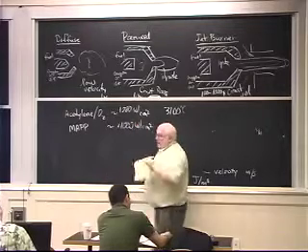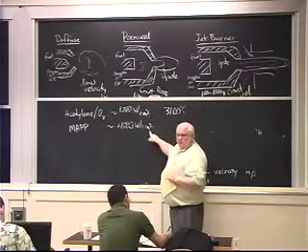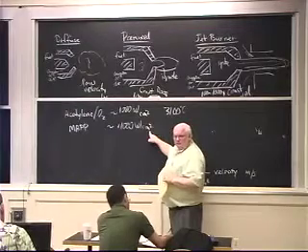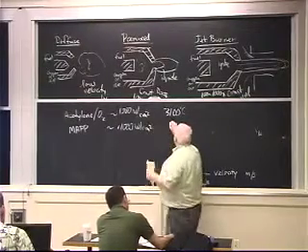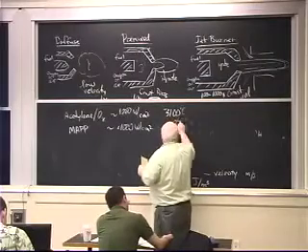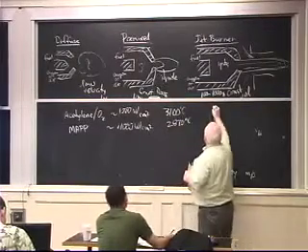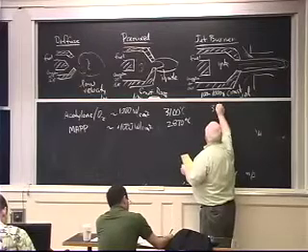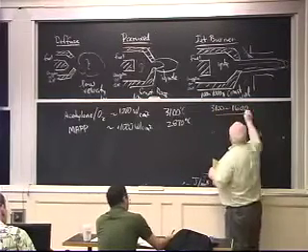It turns out you can weld with MAP, but instead of having a 2 or 3 second time constant, this may have a 3 to 5 second time constant, depending on the torch and everything else. It doesn't have quite the heat. It is 2870, according to the literature. And the useful heat for melting is just the excess temperature above the melting temperature of steel, which is 1600.